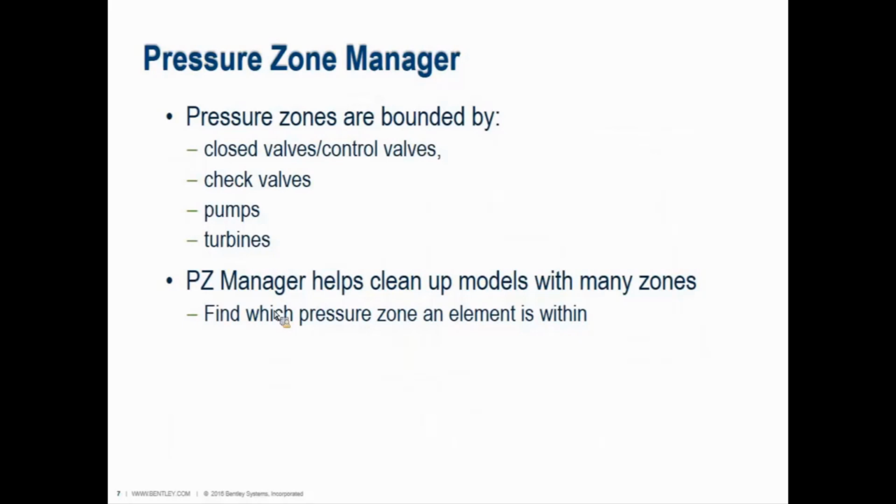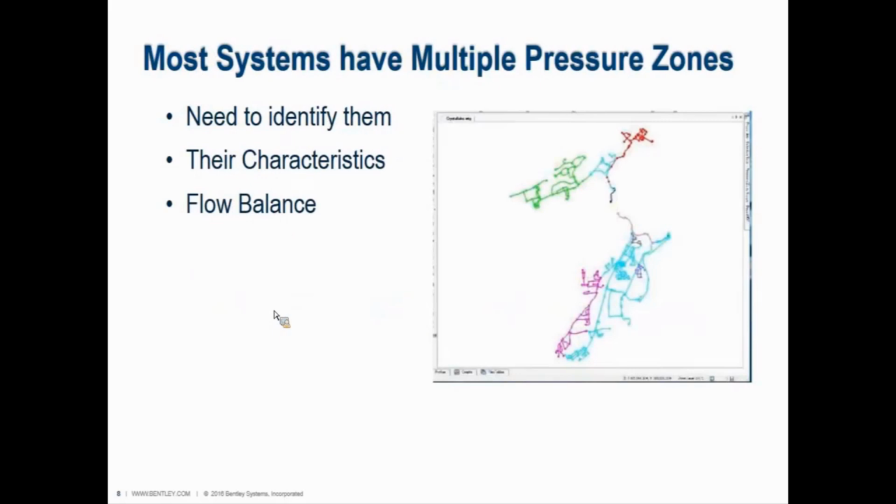So Pressure Zone Manager is actually looking at pumps, turbines if you're into that, check valves or other control valves as boundaries to say, yep, this is all one pressure zone. Pressure Zone Manager will help you find where you potentially have some elements maybe filed under one pressure zone, but inaccurately filed. So graphically, you're going to be able to see where pressure zones exist and where the breakout is. I've got some screenshots to show you here.